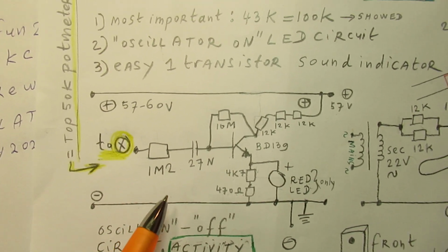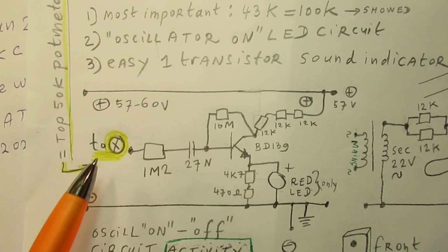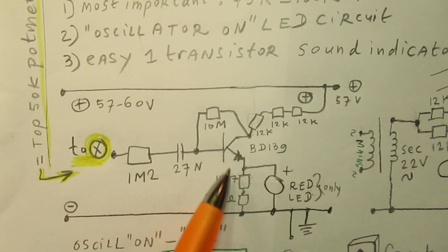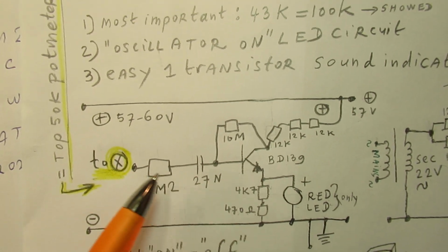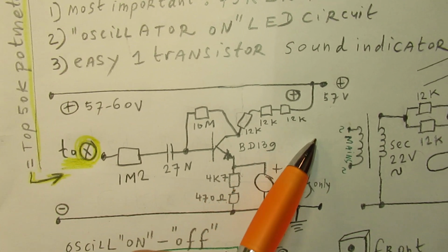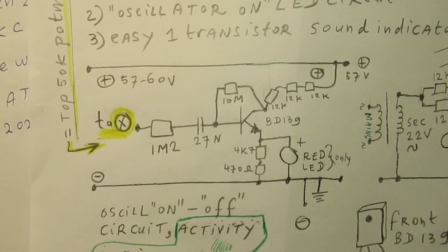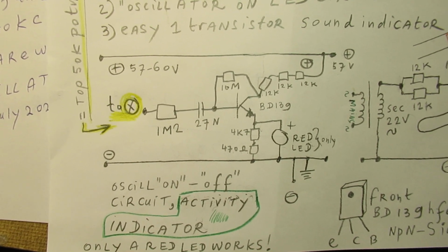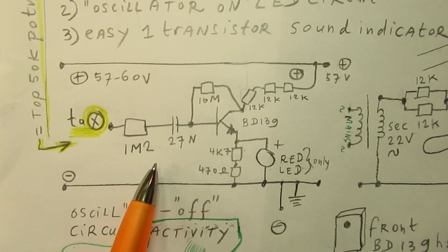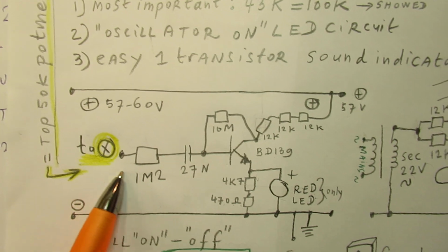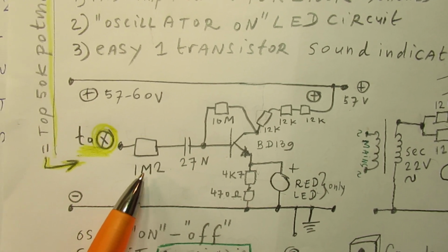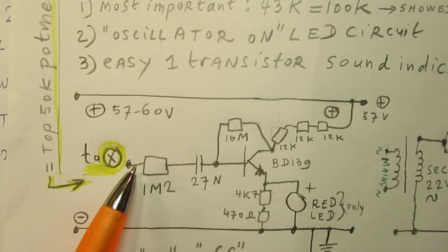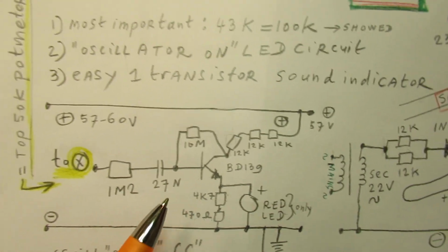Of course I needed a capacitor because I did not want to have any DC influence out of the oscillator. So this is in a certain way also a kind of universal circuit, to indicate AC voltage on a line where at the input there is an enormous high decoupling because of that resistor and that capacitor, etc.